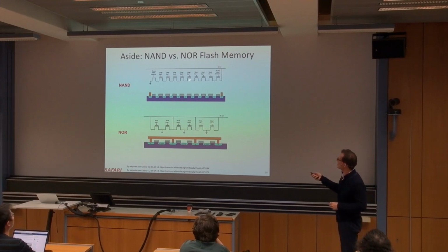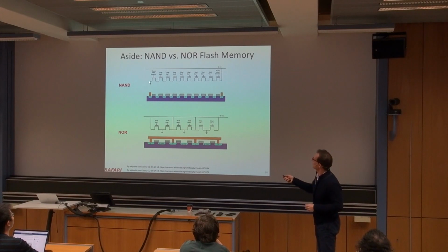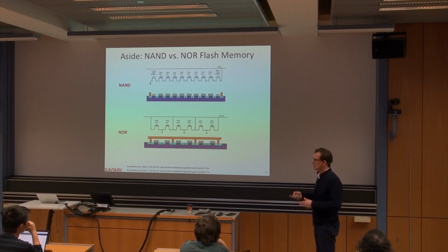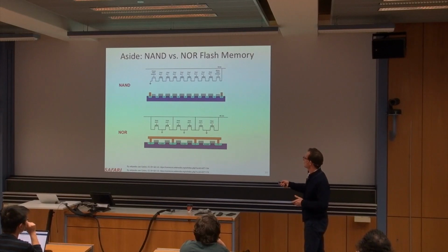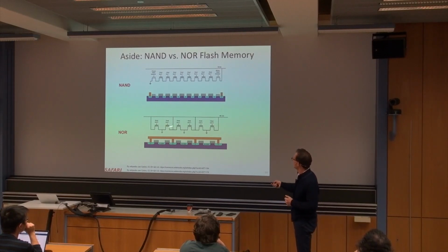And as you can see, the density advantage, the bit line looks like this over here. Basically, this is the bit string that you have. And all of these transistors are connected to the bit line in a NAND fashion, which is what we actually looked at over here, which was NAND. Whereas here, it's like a NOR fashion, basically. You can see that the bit line is like this, and the bit line turns on if any of these transistors actually turn on.